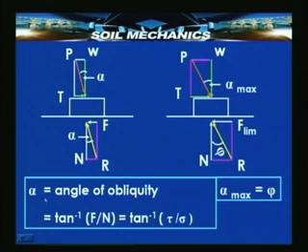When it is equal to phi, it becomes valid for the limiting state, and this is what is known as the state corresponding to limit equilibrium. It is only possible to know the shear stress tau at this particular state, because we know that even a slight increase in tau will cause shear failure here at the plane of contact, whereas at any other value of tau less than the limiting value, we only know that equilibrium exists, we do not really know what fraction of tau has been mobilized.